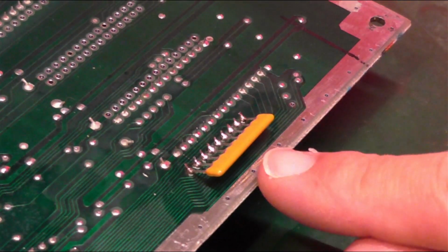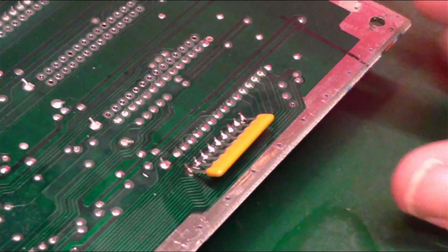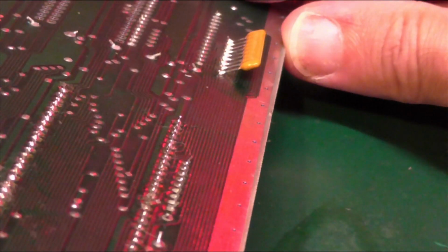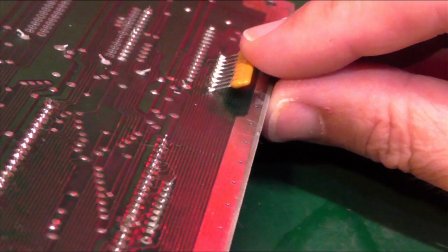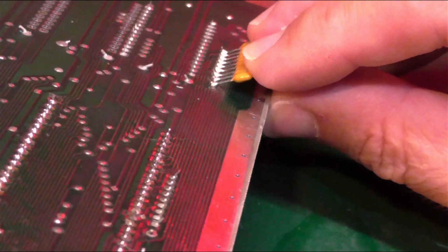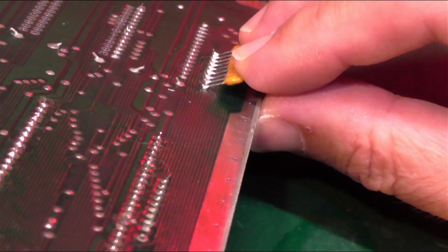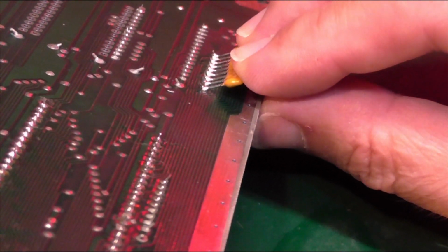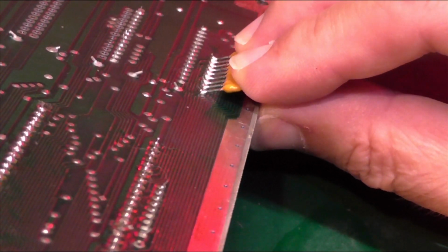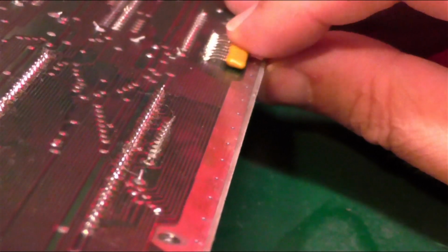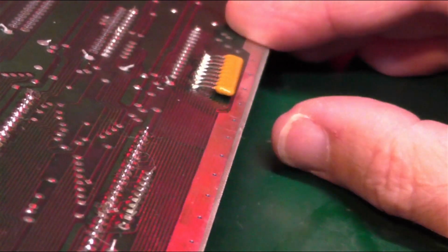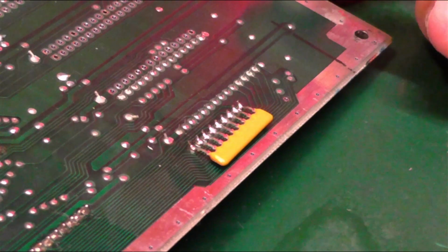So this is the angle that has resulted after that work, and you can see it sticks up quite a long way from the motherboard. So I'm just going to try now gently bending those pins and hoping, well, we'll find out if the solder breaks, then we'll have to pre-bend the next one, but hopefully it's the pins that are going to bend here. There we go, and we've pushed that down flat. So what we now need to see is whether that will fit as it is back in the shielding.